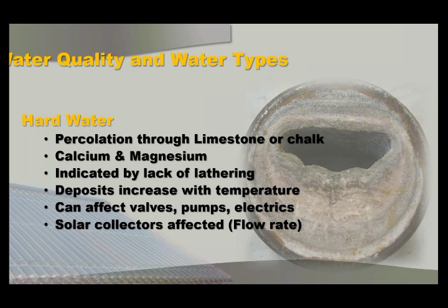An interesting thing to note is that the intensity of the deposit increases with temperature. So the hot water system tends to become bunged up much quicker than the cold system, and of course we're talking about solar, so that gets as hot as it gets in a domestic situation.